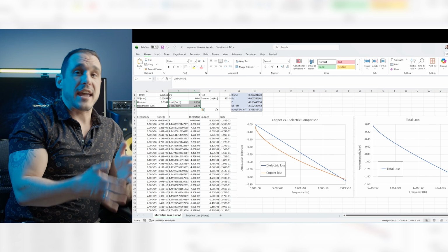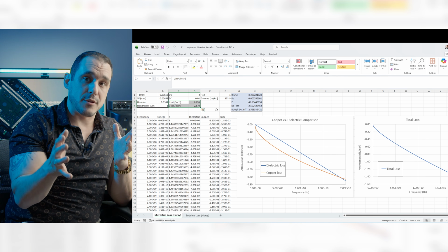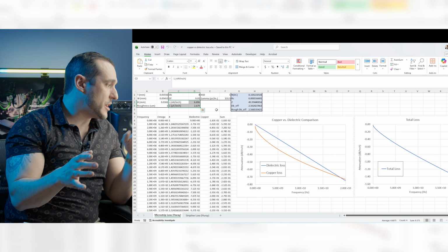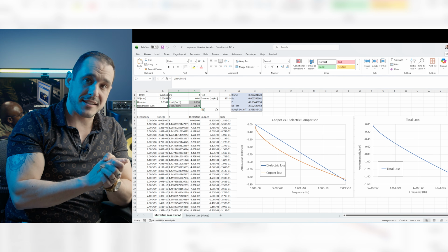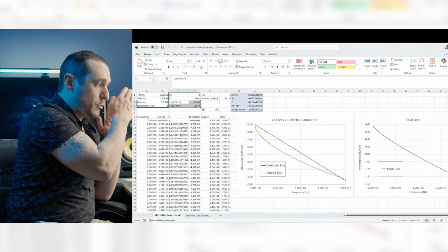Properties panel. The calculator inside the Layer Stack Manager uses Simbeor in the back end, which is one of the best PCB calculators you'll find on the market. That calculator will give you these numbers for the inductance per unit length and the capacitance per unit length. All you've got to do is copy those numbers here into this calculator, and then it will generate all this